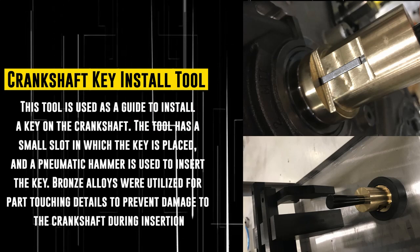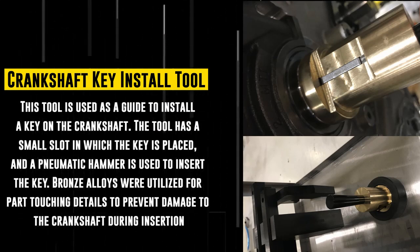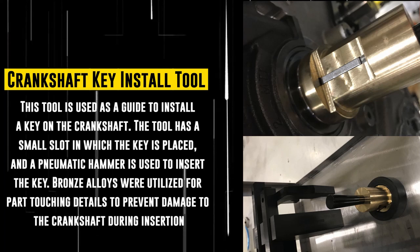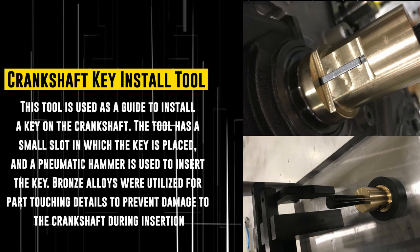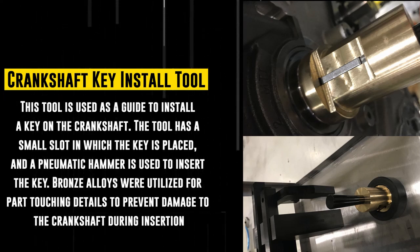Crankshaft Key Install tool. This tool is used as a guide to install a key on the crankshaft. The tool has a small slot in which the key is placed, and a pneumatic hammer is used to insert the key. Bronze alloys were utilized for part-touching details to prevent damage to the crankshaft during insertion.